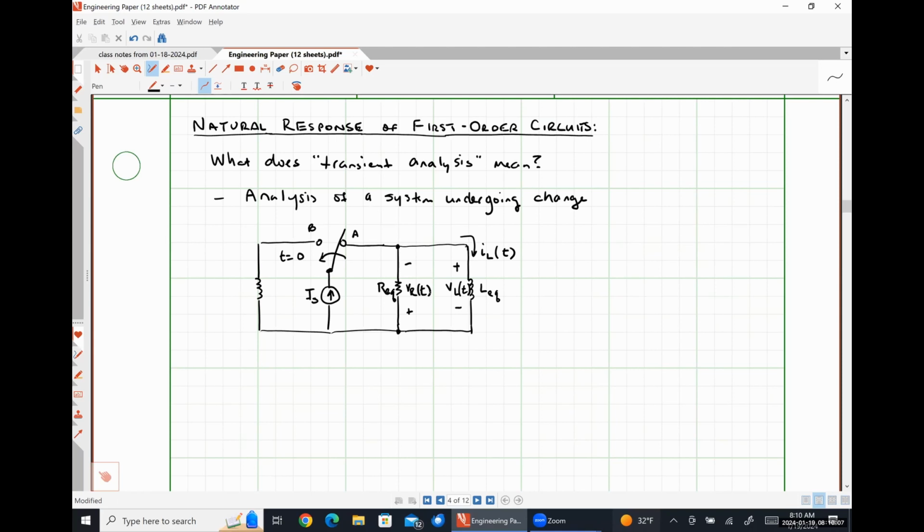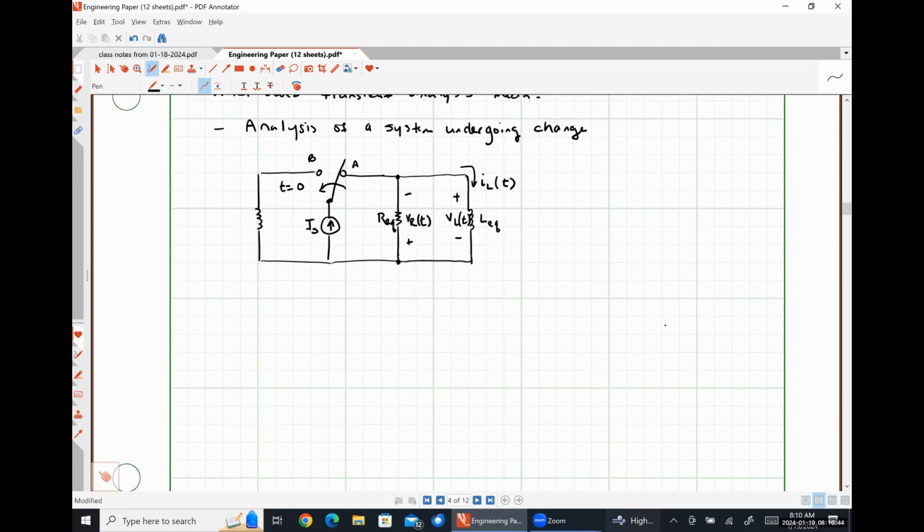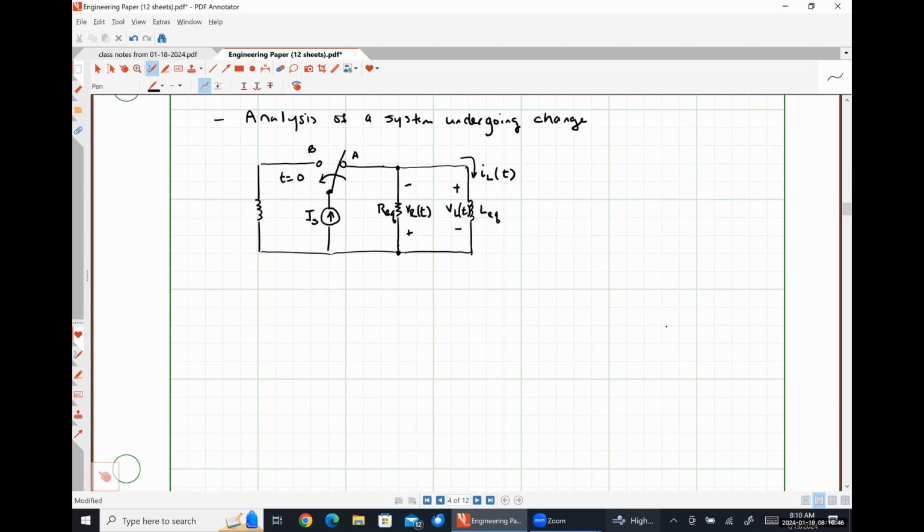The reason I've decided to put the positive polarity terminal of the voltage drop across the resistor on bottom is because during the transient condition, after our switch has changed state, any current that's flowing in our inductor is going to effectively turn around and flow into the positive polarity terminal of that resistor, so that all of my voltage drops are going to look like a positive quantity with this particular polarity. Okay. All right, so we are going to look at this circuit at 3 points in time.